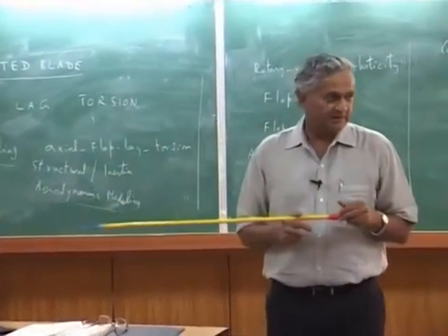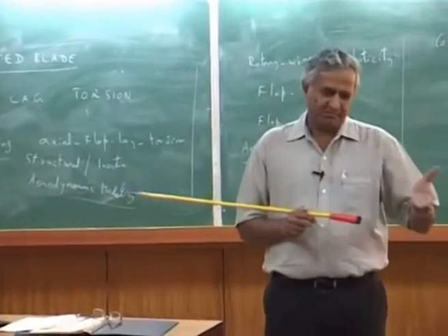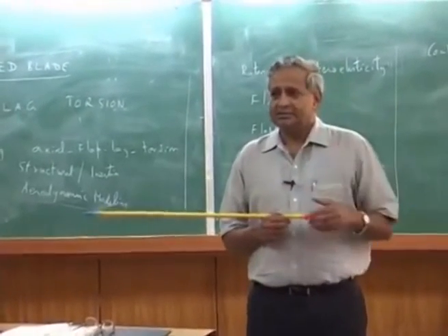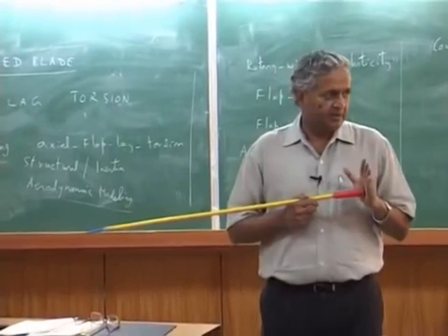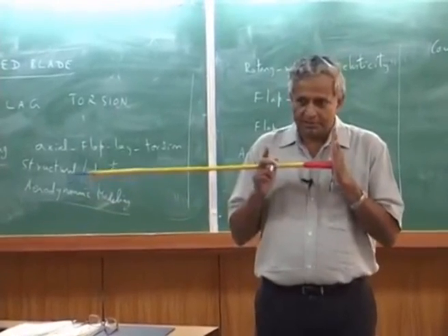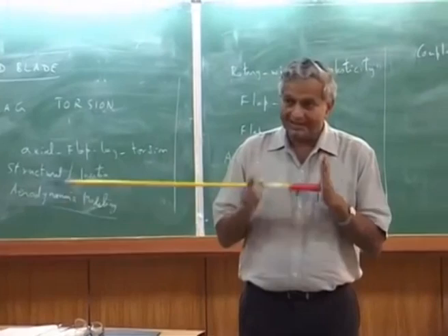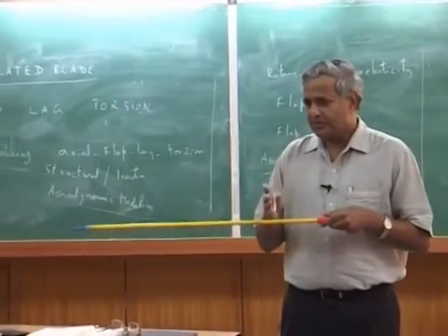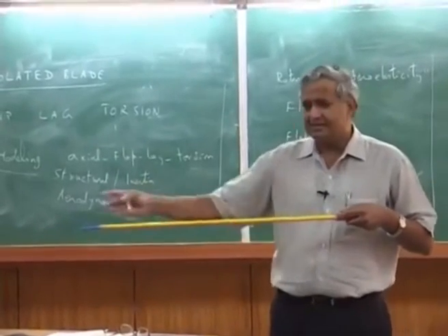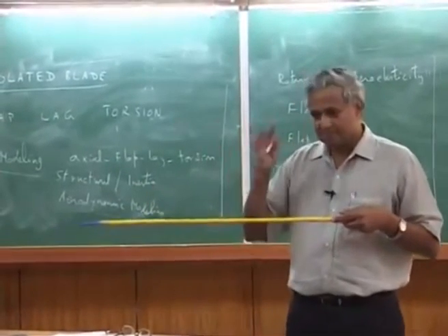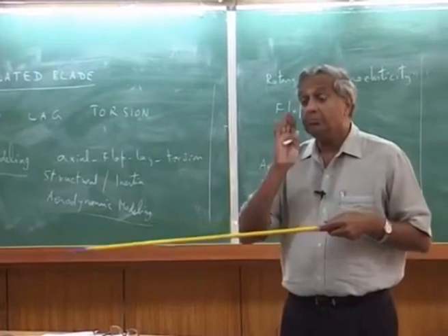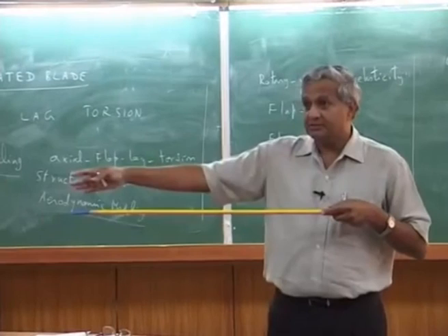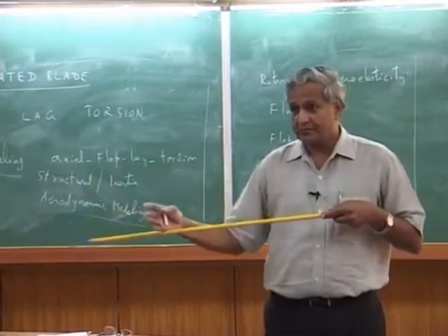But recently, maybe over 10 years ago, an experimental program was conducted on one UH-60 helicopter, by the US Army, in which they had some 220 ports, so many accelerometers, I don't remember exactly, I have a figure, on the blade, both chordwise and spanwise, pressure ports, accelerometers.